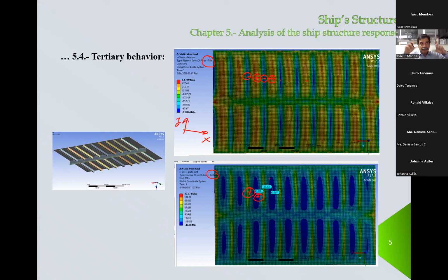So you see that that's a typical plate bending response. Okay, that's a result, remember, of the kinematic hypothesis. On the thickness, you have a linear distribution of stress. On the top and in the bottom, you have most probably about the same value, but the sign is the opposite. That's what we're seeing. And the other thing that we're seeing is that here and here, about this value and about that value, they are about the same.